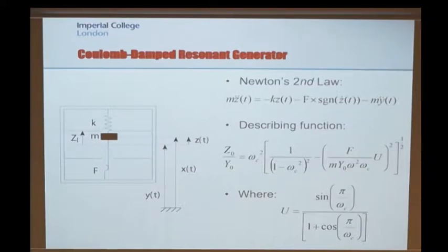And a lot of the work he did, he was a mechanical engineer, so he was looking at sliding friction, and he would set up experiments where he had an object on a table under Coulomb friction on a spring that was pulling it back and forth, and he would analyze the movement of that and worked out all the maths for it. Quite interestingly, 70 years later you can actually apply that same maths to a MEMS device using electrostatic transduction. So you can calculate this, and again, the details of the calculations here are in that paper that's referenced at the start of this section.